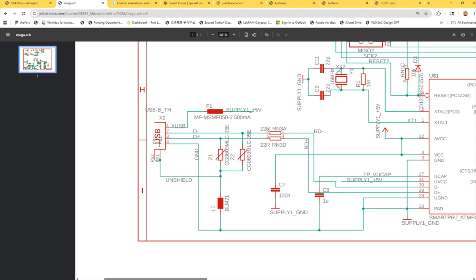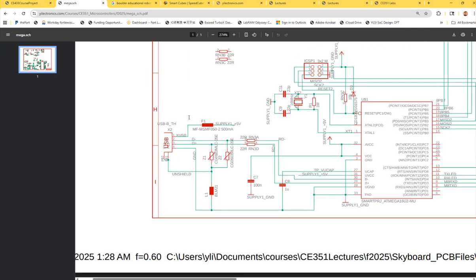You just go back to your library, the project file, and you delete your board file, right? Delete it, so it doesn't exist in your design anymore, and then recreate another layout file to make it consistent. But all your manual layouts and the placement will be gone. So everything will be at the bottom left corner, and you have to replace them. But this is something you can do, right? But try to save copies and backups at a safe place. Always keep both windows on.